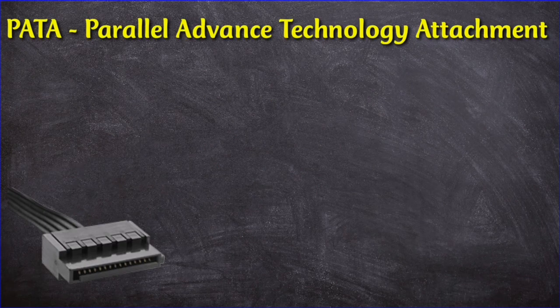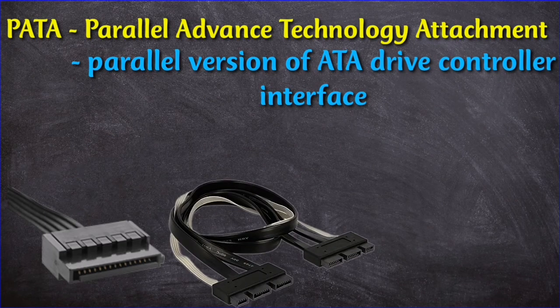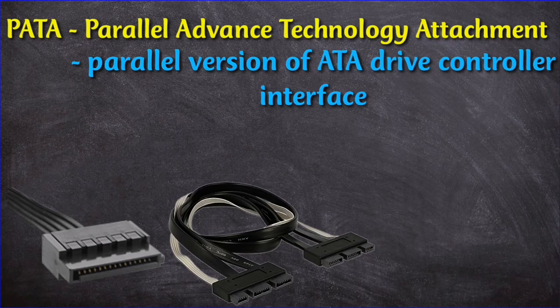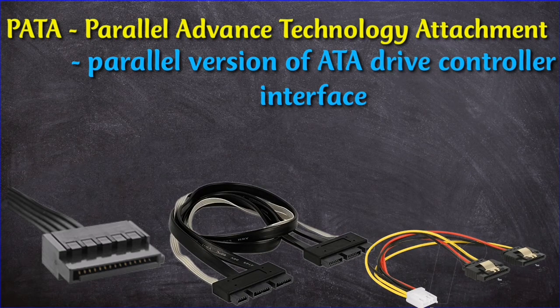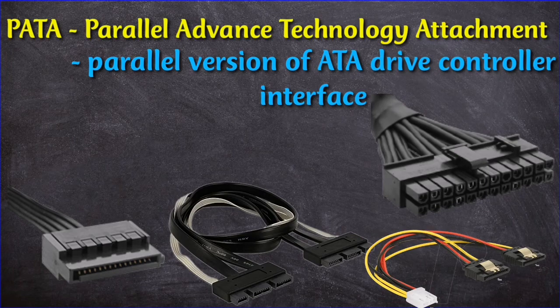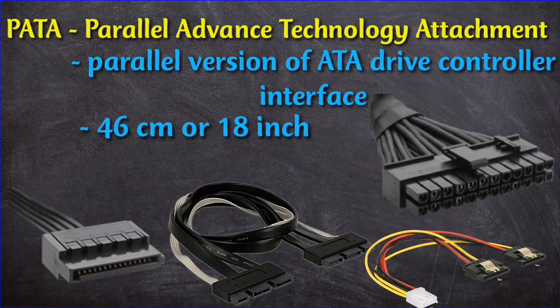PATA or Parallel Advanced Technology Attachment refers to the parallel version of the ATA drive controller interface. As its name implies, it is based on parallel signaling technology. The connections for PATA devices were originally made using 40-conductor ribbon cables. These were later supplanted by 80-conductor cables in which every other conductor is grounded, minimizing mutual capacitance and consequent crosstalk between conductors. The maximum workable cable length is 46 centimeters, which is about 18 inches. This means that PATA cables are only practical for use with internal drives.